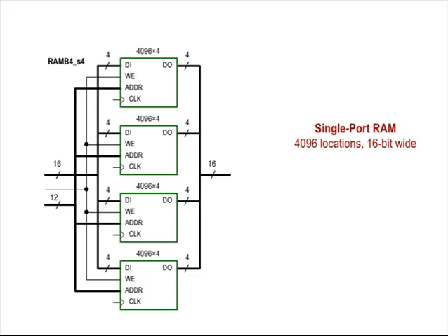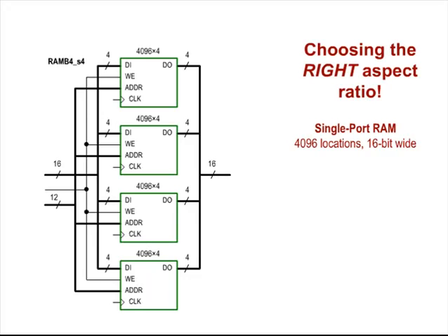This slide shows how choosing the correct aspect ratio solves everything. The 1024 by 16 memory is now making use of the internal multiplexing structure of the block RAM blocks so that no other logic is required. In this case, that is with a 4-bit output. So at every sample, each block RAM will contribute 4 bits to the output. This saves you from building any input decode logic. Likewise, the 16-bit output is wired together without any muxing.